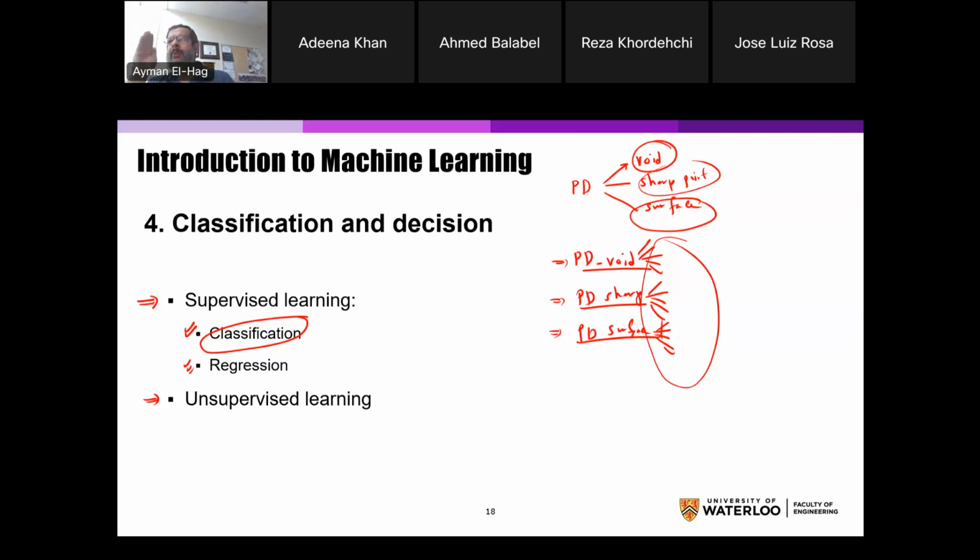So it is equal to 0.16 milligram per centimeter square, a number. A classification would say that the ESDD is high, medium, low, very low, for example. Now, in outdoor installations, I will select the classification problem only in today's lecture because most of the practical problems we have in the outdoor installation are classification problems.